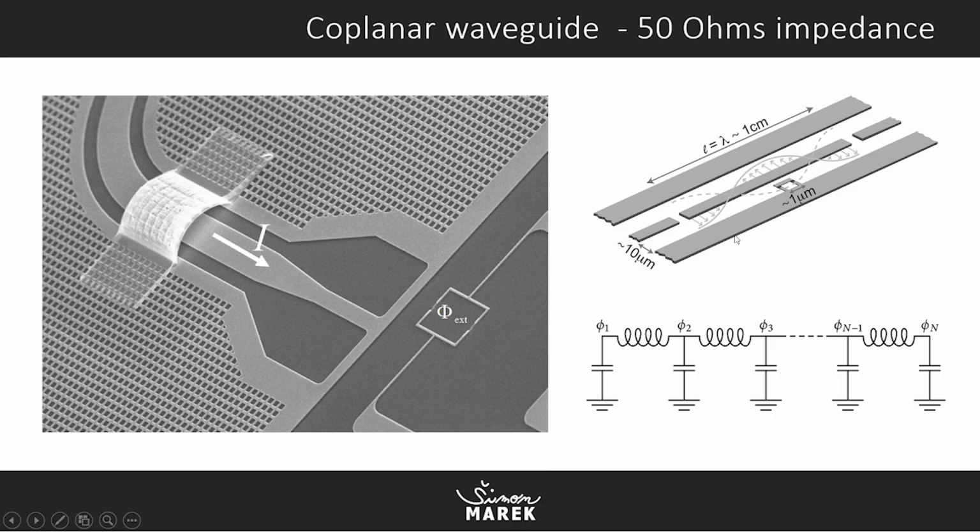There is a representation for resonators or meanders. You can see this inductor and capacitor, and these basically are coplanar waveguide or trace, and here is the lumped representation for it. We can measure 50 ohm impedance using VNAs, vector network analyzers, and yeah.